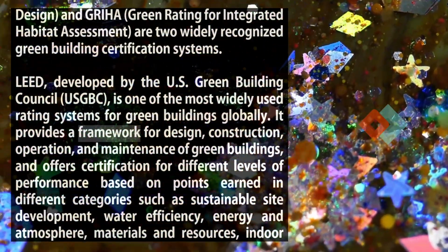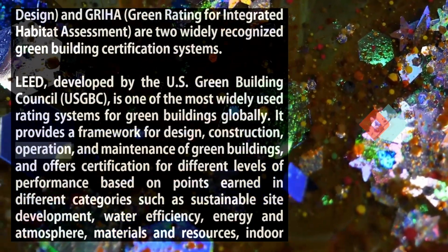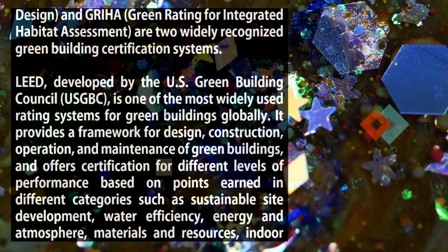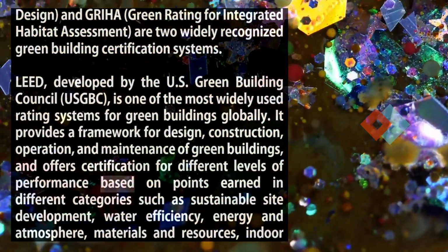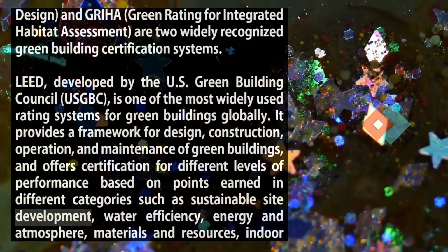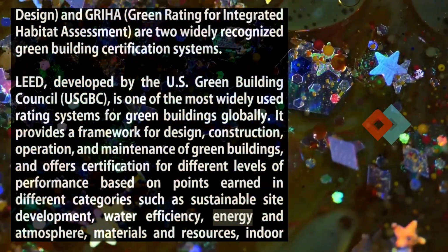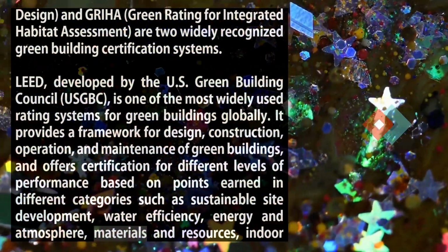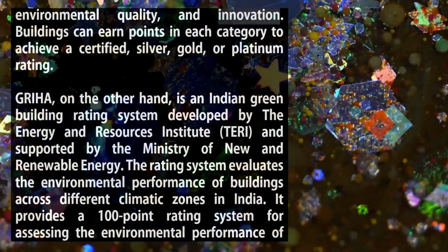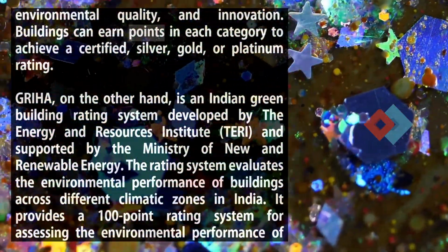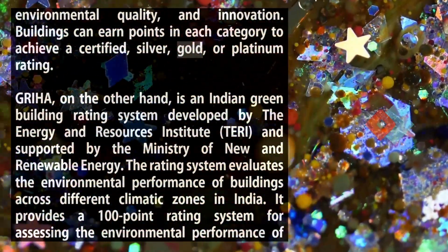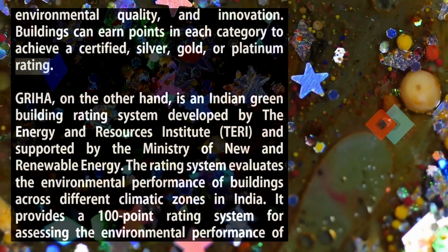It provides a framework for design, construction, operation, and maintenance of green buildings, and offers certification for different levels of performance based on points earned in different categories such as sustainable site development, water efficiency, energy and atmosphere, materials and resources, indoor environmental quality, and innovation. Buildings can earn points in each category to achieve a certified, silver, gold, or platinum rating.